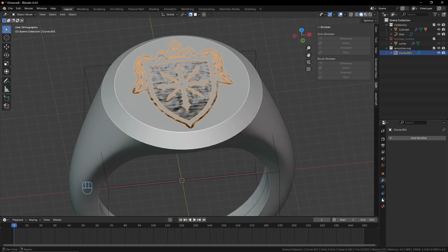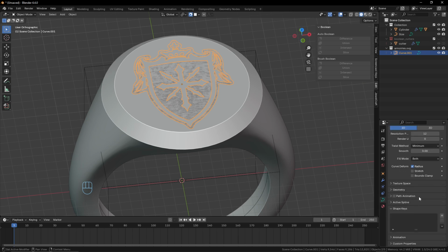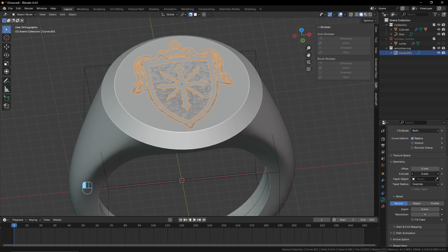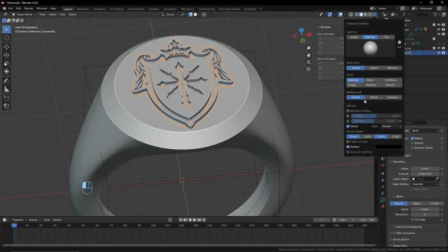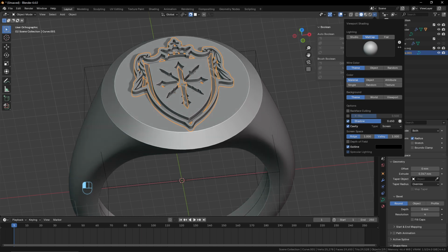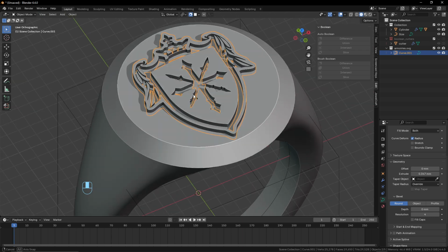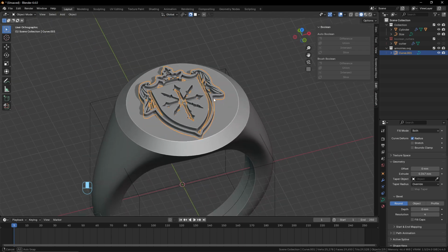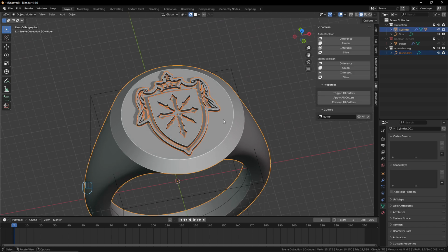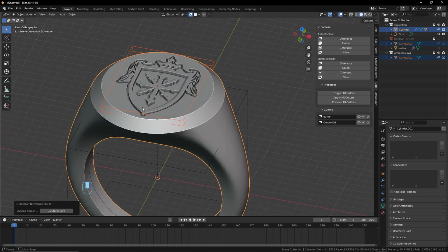So what we will do now in the curve options, we'll remove the material and go into geometry, into the extrude here. And we can also enable shadow here to see a little more what we do. Now I can select my first object and my second object. And again, I will make a brush boolean here. And you can see that it works perfectly.